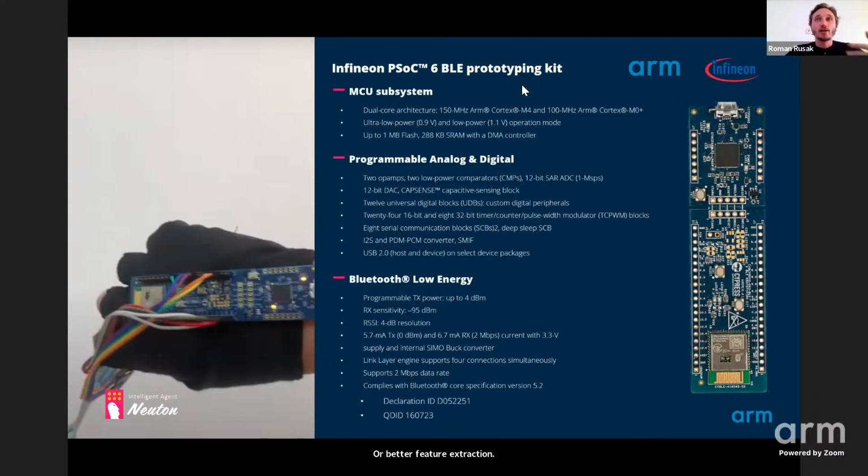Let's go to the wireless SoC that we use for this demo. For our demo project, we use the Infineon PSoC 6 wireless SoC. This SoC has many advantages for our smart toothbrush concept. First of all, it utilizes a dual core ARM architecture. And we already mentioned that it's well suited for battery powered devices, the way it's energy efficient.